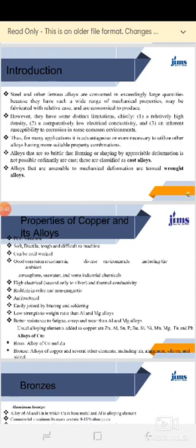Non-ferrous materials, actually those are materials which do not have carbon atom as its main constituent. Properties of copper and alloy: FCC structure, soft, ductile, tough and difficult to machine, can be cold worked, good corrosion resistance in diverse environments including ambient atmosphere, seawater and some industrial chemicals, high electrical and thermal conductivity,